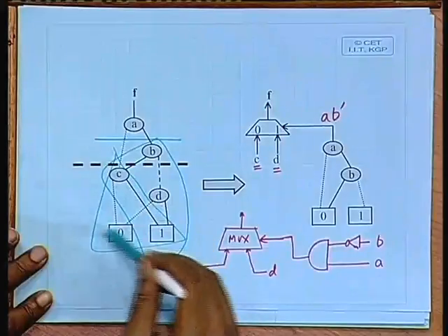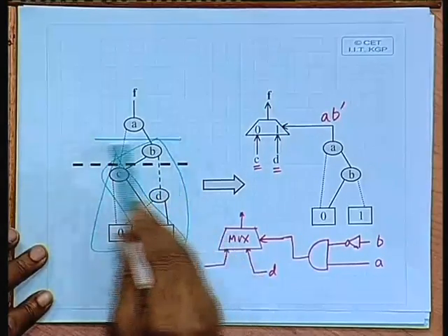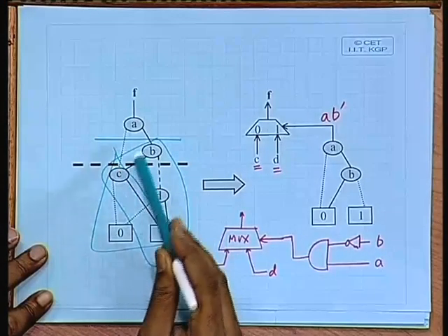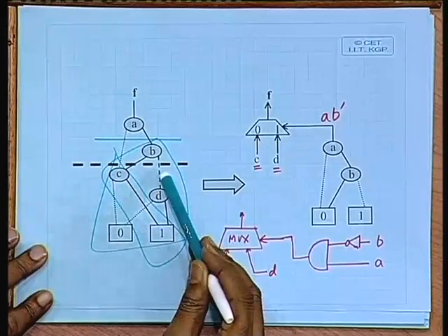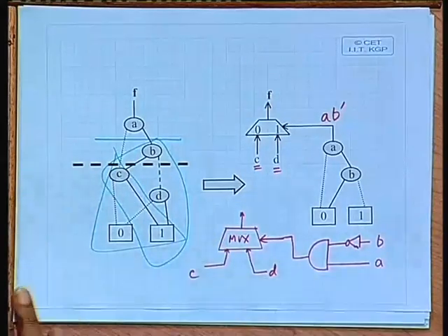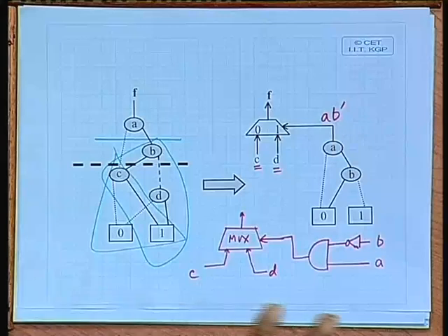That means again the best point to cut will be the place where there is minimum overlap between the two. If you cut at A, you will see that this C node is common to both. So, you will have to cut in one place where there is minimum overlap between the two, and approximately they are of equal sizes. There are some heuristics which are used for that.